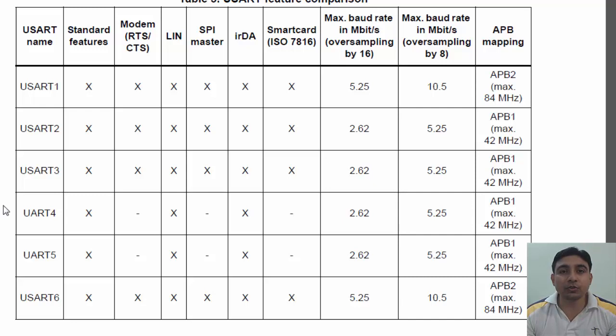Actually, let's use USART in this tutorial. I would use USART to do UART communication so that you can see how configuring both is nearly the same. Okay, so let's choose USART3 to do UART communication.